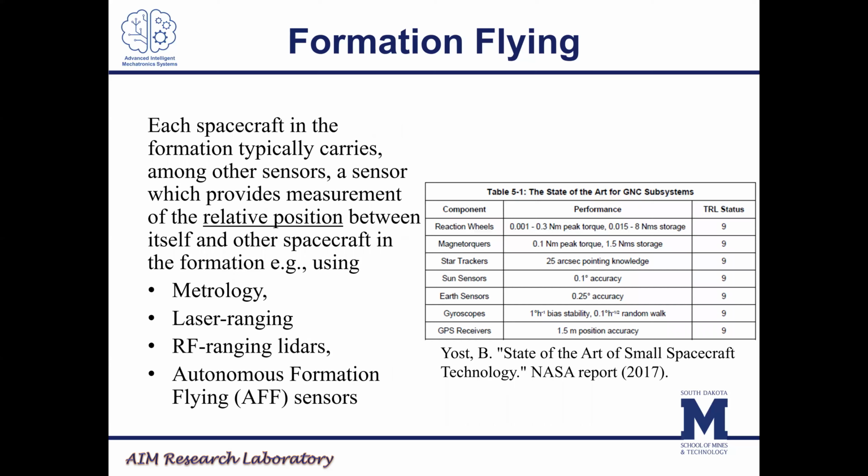But in any case, if we're going to try to have these satellites be in a relative formation with each other, one thing we need is some kind of relative position estimate method. So that could be with a LiDAR, where we've just got a distance from the object. It could be with a sun or a star tracker, where that gives us a pretty broad relative position. But if you're near Earth, one of the good solutions so far has been to use GPS. It works just fine in space. A little bit of a better antenna, but it's fine. You still get 1.5 meter accuracy, which is just incredible.